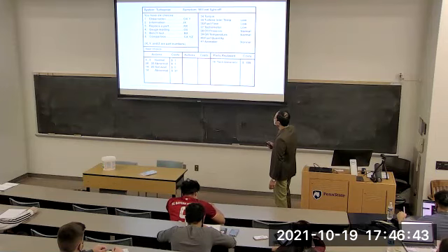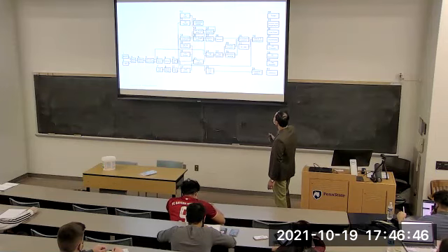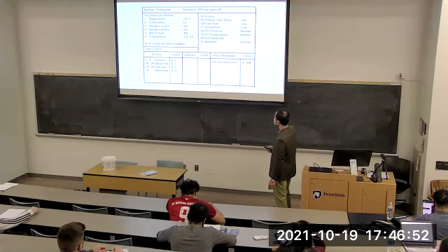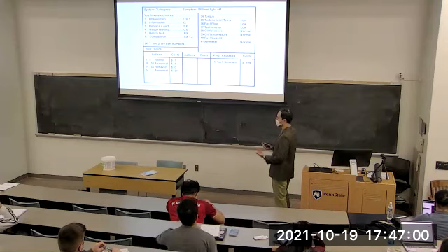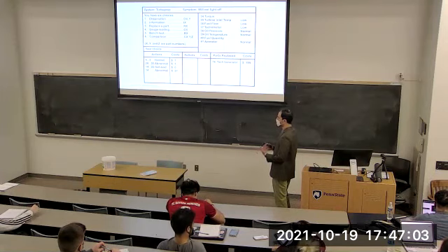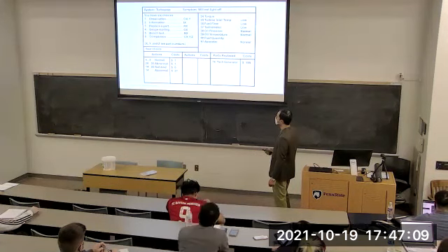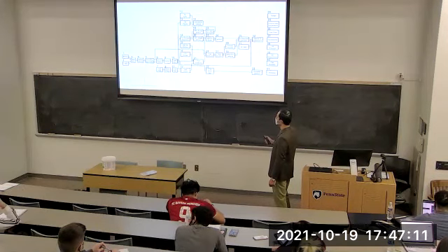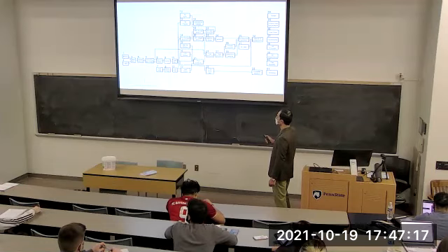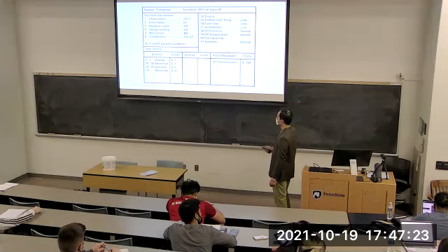26 and 30 is saying abnormal, which was this. It's going back in this line, basically. That's why it's trying 14 and 20. It says not available. My guess is that it means it's having a 0 output or is not working properly, because in the next step it reaches 14 as abnormal, which is this. So when this is not available or is not working, then this tachometer generator is the faulty component, which is what they recognize here.